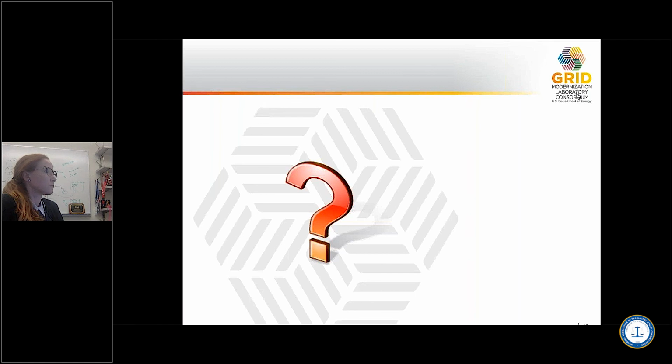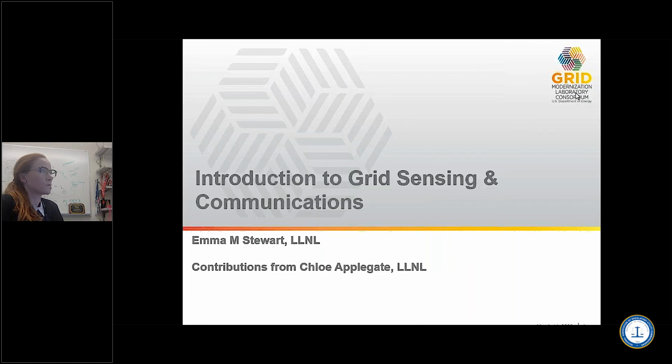Thanks. Next question is, what percentage of load is generally considered safe, or what would we recommend for safest use of a distribution system transformer? Can you tell me something about auto transformers? Yes, so the safe load of a transformer is a very large discussion. For steady state load, you want to keep it below 100% because the rated load is what it's designed to cover for an indefinite period of time.